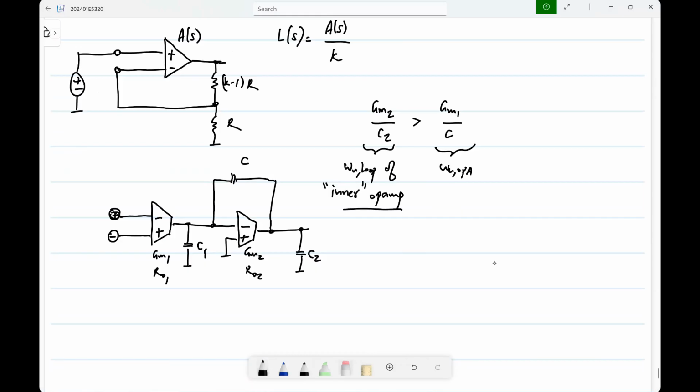Like I already said, when you are analyzing only the op-amp, we talk about the unity gain frequency of the op-amp, but that itself is not relevant. What is relevant is the unity loop gain frequency. So you have to implicitly assume that whenever I talk about it, I'm talking about putting this op-amp in unity feedback, because the unity gain frequency of an open loop system is not quite relevant, certainly not for stability, right?